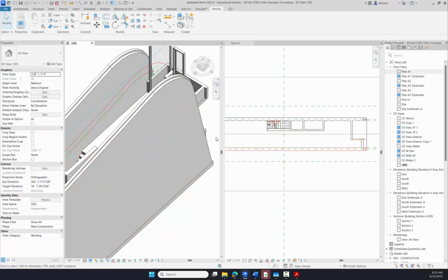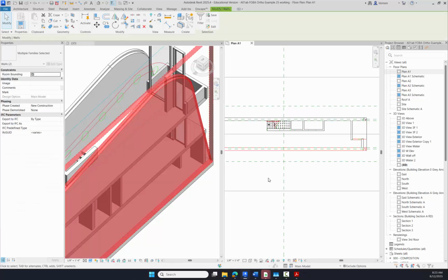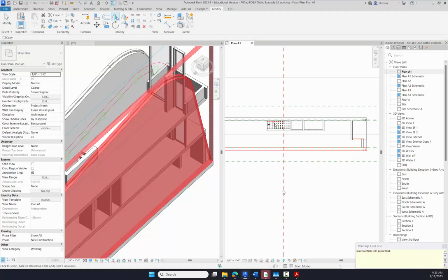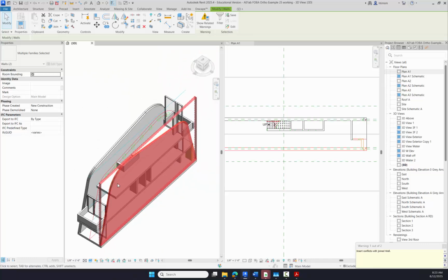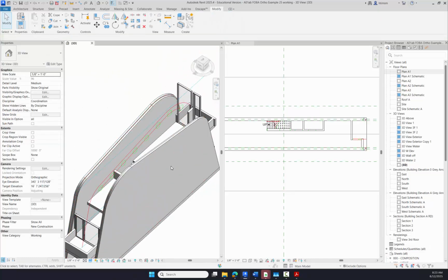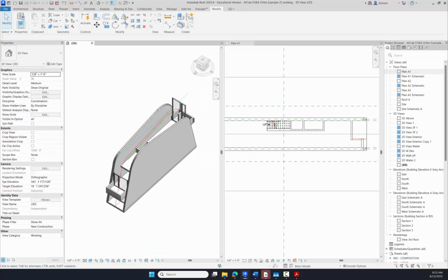All right, I lost my selection, so I need to make it again. That was the problem. Let me grab those two guys, left click over here, go to mirror, pick axis, make sure the copy is not selected, and pick that, and it will reverse that. So I don't have to remake the sweep, right? Now we've got those two guys with the reveals in them.